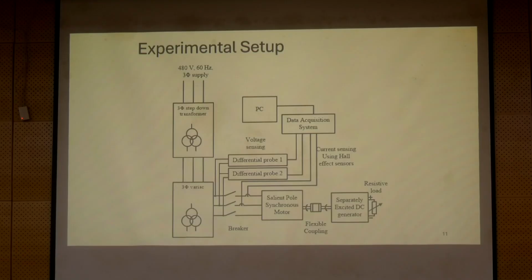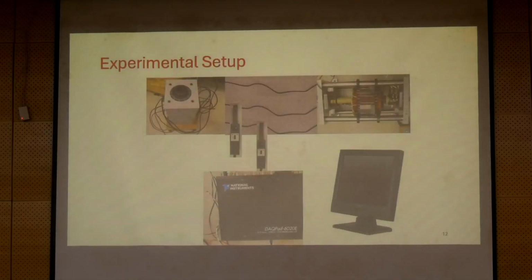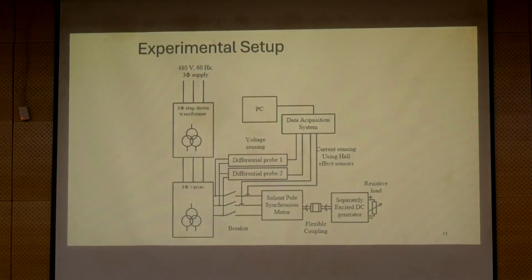You will have fast acting circuit breakers along the lines, loss of excitation. In a lab setting, it's okay to do that, but it's better to have loss of excitation detection and appropriate protection for that as well. And then mechanical protection, wearing safety glasses just to protect your eyes. These are some mandatory procedural parts. Okay.